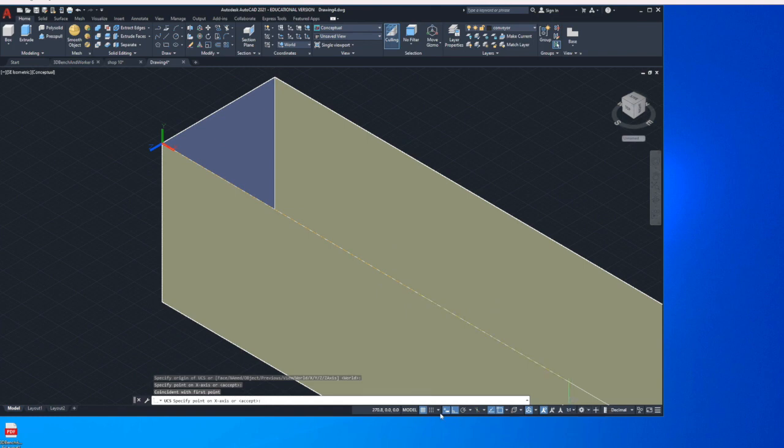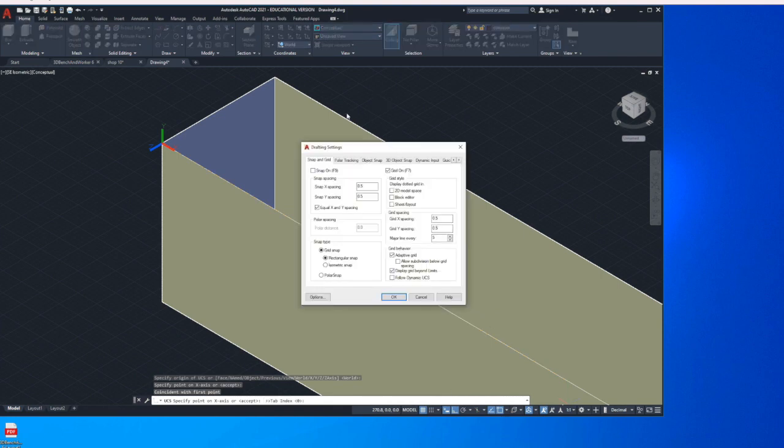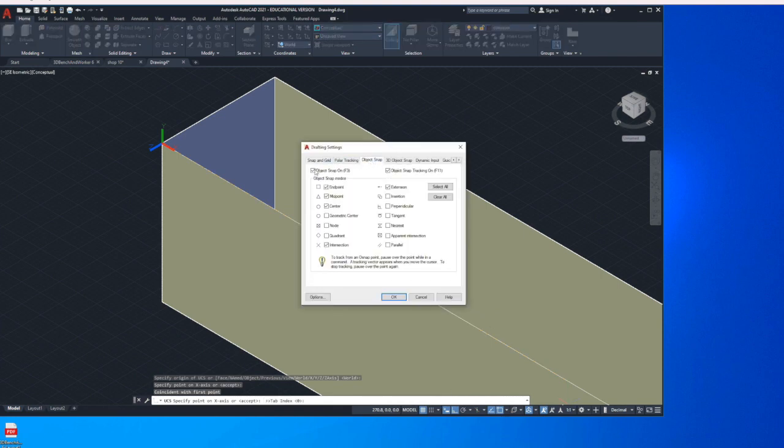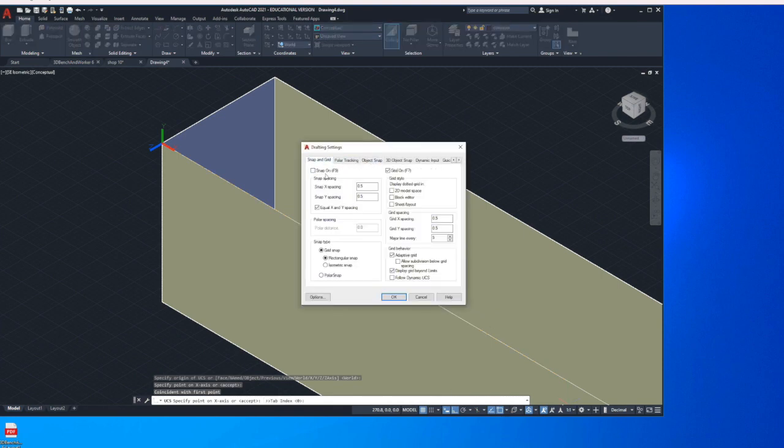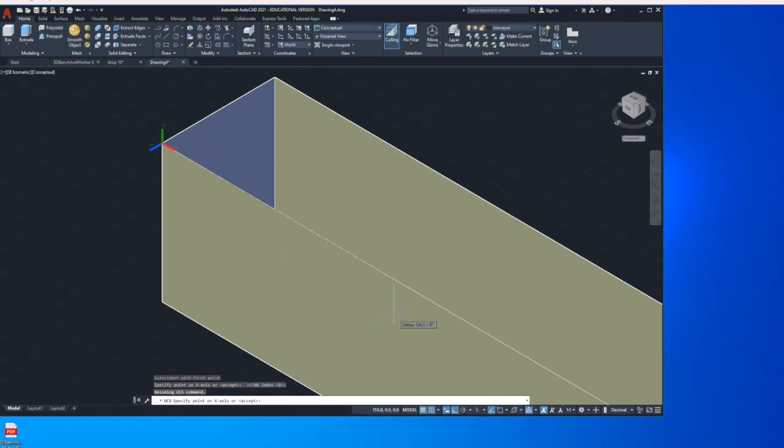Okay, now I've got my object snapped on, so it doesn't want to snap on an edge. So I'm going to come back down here and shut off my object snaps. Let's go to snap settings, object snap. I'm going to shut that off, but my grid snap, I'll make sure I turn that on, and it's set for 0.5 increments. And I still have the ortho command on. I assume I've got the ortho command on, and it says yes. Okay, so let's try this again.